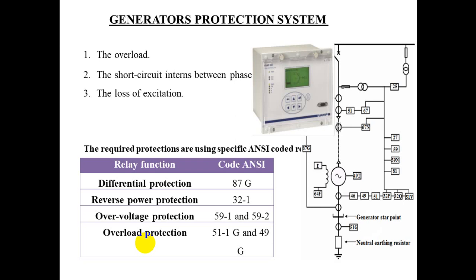Further, the overcurrent relay would most probably operate for a loss of field on the machine, disconnecting it permanently or prematurely. To overcome this problem, it has become customary to apply an overcurrent relay in combination with an undervoltage relay, the latter relay controlling the fault setting of the former, as shown in the figure below.